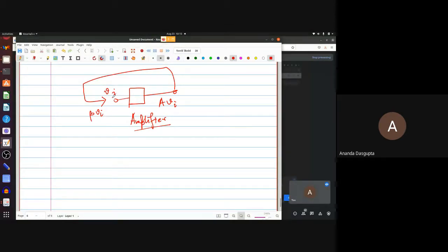Sometimes it becomes important to bother you. If you amplify it too much, you would hear the hiss, the annoying sound that you get. That's the thermal noise being amplified too much so that you can hear it over on your mic, on your speakers. But basically you have thermal noise which is tiny. But if you can manage to amplify the thermal noise, but more importantly, bring it back again so that it can feed itself, then the output is going to keep on growing, and it's going to grow without bound. And you are going to get an output without any source. Okay, that's how an oscillator really works.